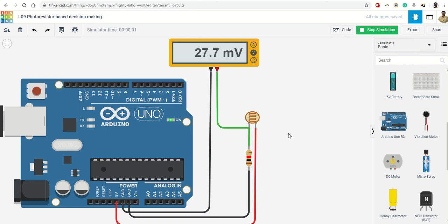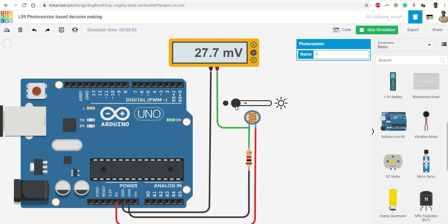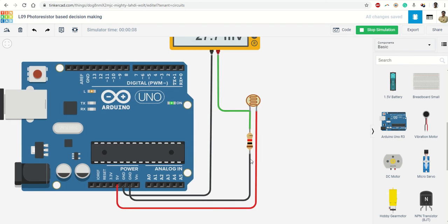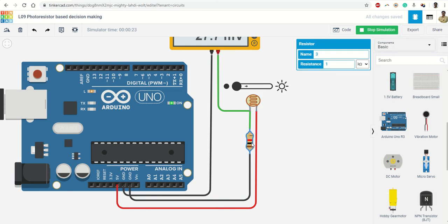So we can see this is complete darkness, and in this complete darkness the positive voltage is connected on this terminal, and we are basically measuring the voltage across my fixed resistance. The variable resistance value is 180 kilo ohm, and this is only 1 kilo ohm.